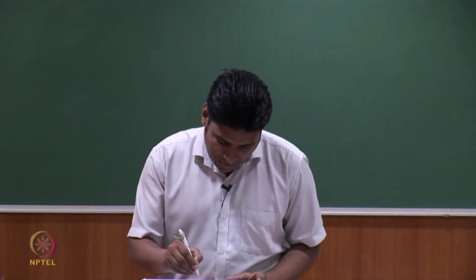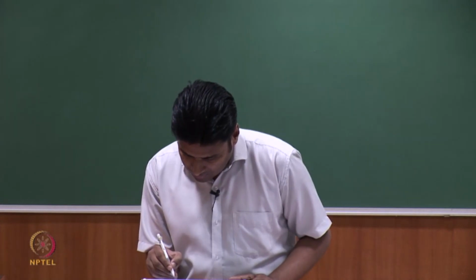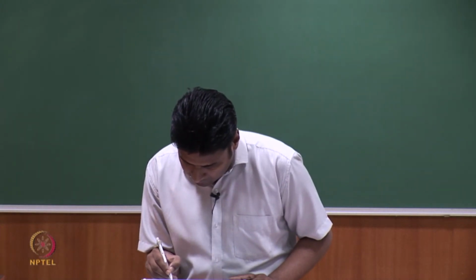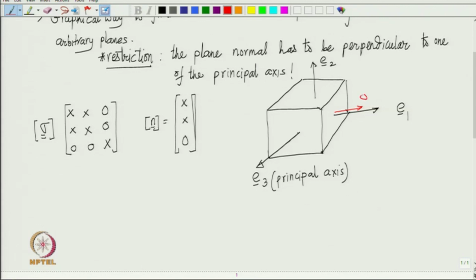So, if we write down all the traction components, we have sigma 1, let us call it sigma xx, because that is how people do it in many books also. So, along 1 it is x, along 2 it is y, and along 3 it is z. Okay. So, this becomes sigma xx, and then it has tau y x, right, on the x plane, but in the y direction.